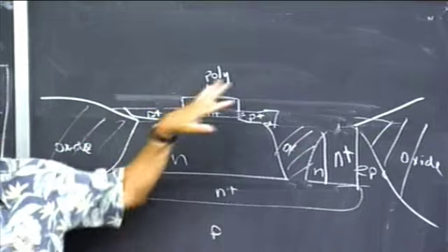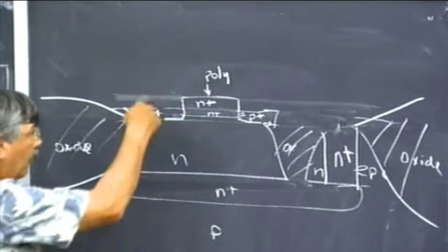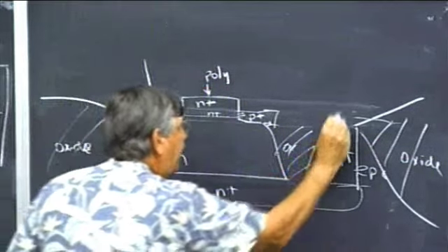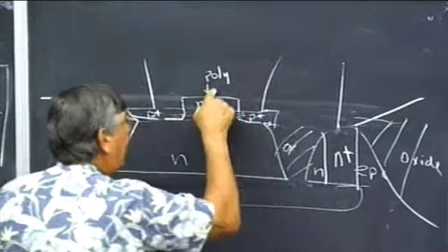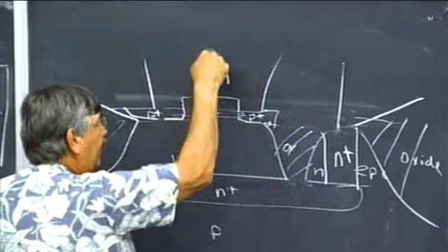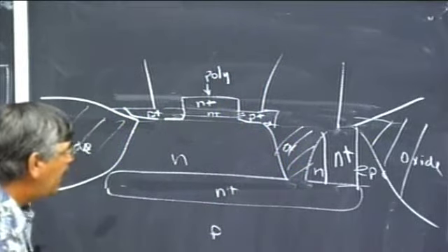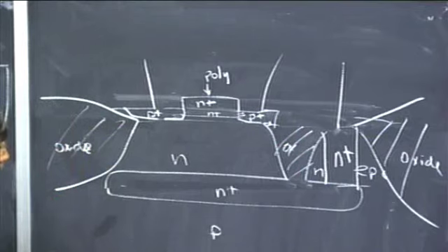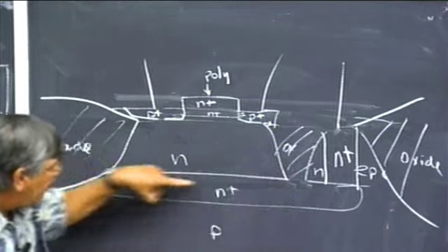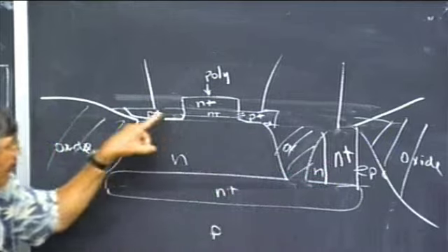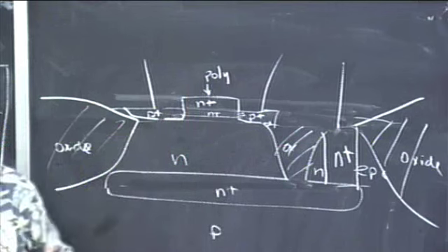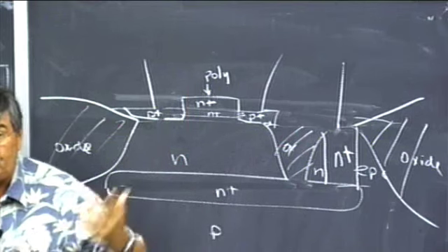Polycrystalline silicon, you can use this as the emitter contact, or we can put some metal off to the side. We'll put metal here, metal here, metal here, and somewhere maybe in the third dimension, eventually we'll make a metal contact to the poly, and that'll be our transistor. And that now has this N+ as close as we can get it, the P+ as close as we can get it. The emitter is automatically aligned, so that's how I know the P+ is as close as we possibly could have had it.